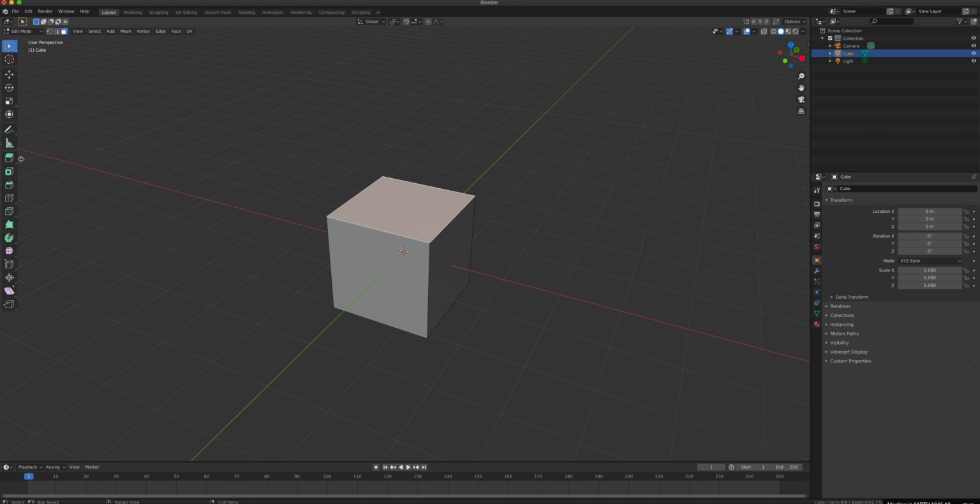Okay, and then if you're not sure which ones are the tools because they don't have a name, they do have a tooltip. So just hover your mouse on top, and then you will see the tool, like the bevel tool we used last week. Okay, so I'm going to go with extrude right here. So if I click that, it doesn't do the extrusion.